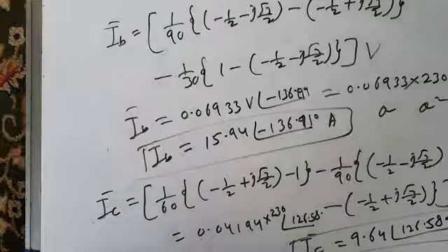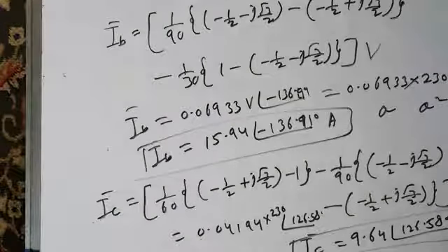So in today's lecture we have solved three-phase unbalanced systems. First we took three-phase unbalanced star connected load or Y connected load, and we developed some equations. We used mesh current analysis, and using it we found mathematical expressions for line currents IA, IB, IC in terms of phase to neutral voltages VAN, VBN, VCN, and the load impedances ZA, ZB, ZC. Three equations were found for IA, IB, and IC.